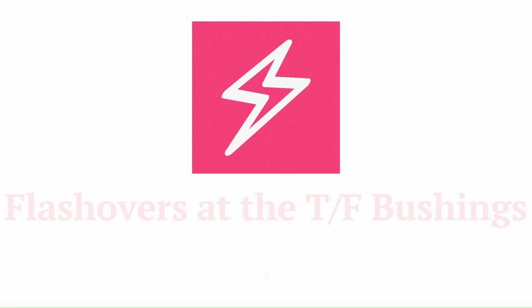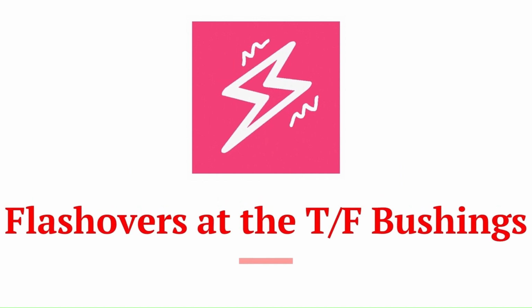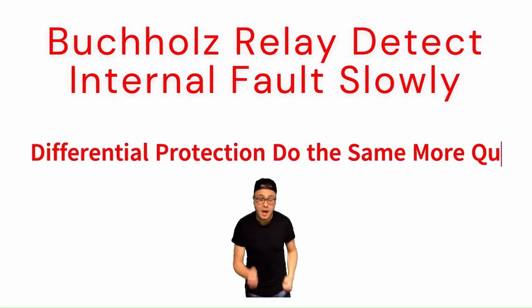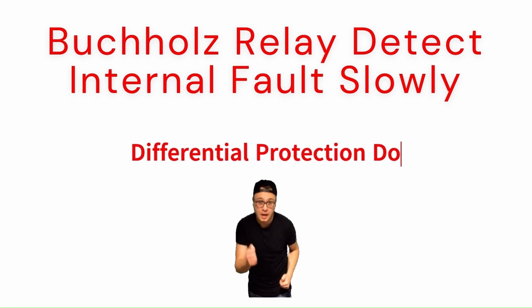Buchholz relays do not adequately cover flashovers at the bushings. But differential relays can detect these types of faults. Although Buchholz relays detect internal faults in transformers, differential protection schemes do the same thing but more quickly.